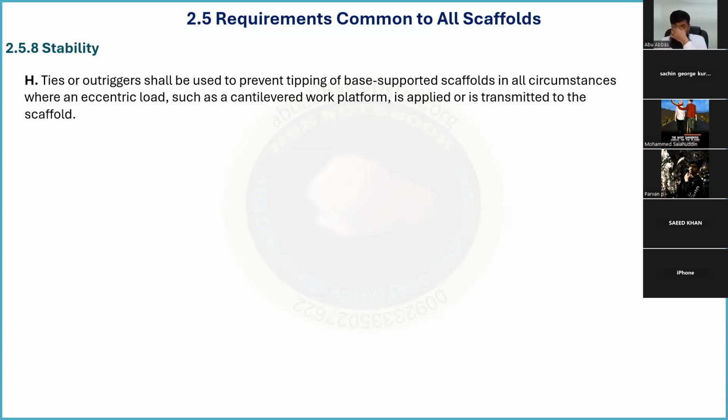Cantilever we know, one which is extended. This platform has to have its own load capacity, but when it is loaded, there will be an uplift load at the back, the support side of the platform. So this is an extra, critical load on the scaffold.